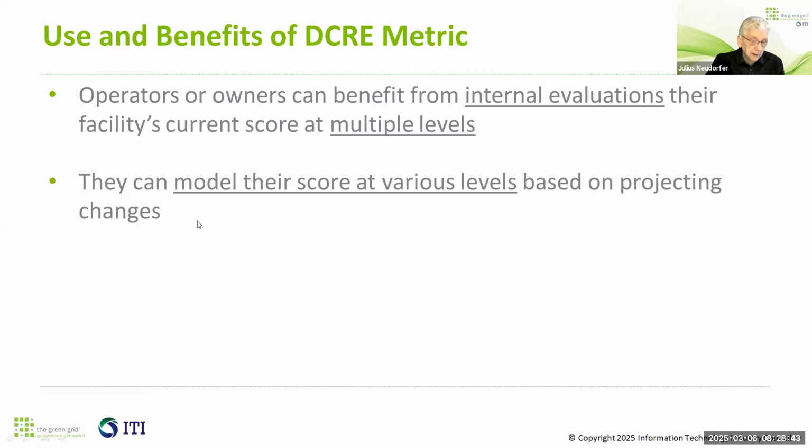So if you're using 1 liter per kilowatt hour, and you can bring it down to 0.7 or 0.5 just by changing the performance characteristics of your cooling plant, that's optimization. You're modeling the change, I should say, but you really still have the existing design. On the other hand, if you have a choice between building a cooling plant that revolves around evaporation as opposed to using no water at all, well, then that becomes a planning tool.